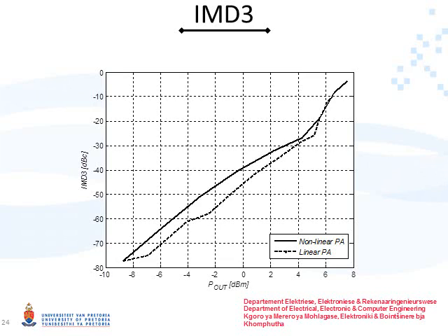The third order intermodulation distortion component is shown in this figure. A 100 MHz tone spacing was used in the two-tone test to analyze this component. The use of the APD linearisation technique results in a reduction of the third order intermodulation distortion component. Optimum reduction is achieved for output power between -7 and 3 dBm, with a maximum third order intermodulation distortion improvement of 10 dB being achieved.